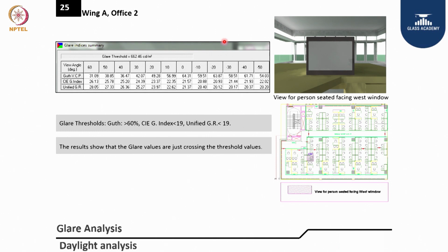Recently you have the WELL rating, and even LEED version 4 is directing towards this, on how the window should be positioned. Depending on the window-to-wall ratio, glare control devices need to be implemented, which can be automatic control, like a blind, and also the angle at which you place your computer. Working at about 120 degrees from the facade, you will get less glare.